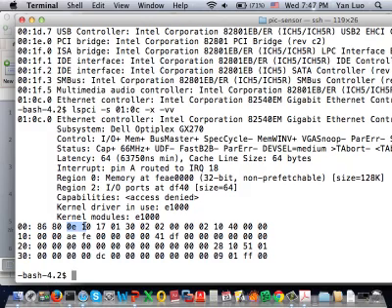And the following 2 bytes, 100E, is the device ID of a device produced by Intel. Intel has the authority to assign these codes to their devices. And by checking their database, the operating system finds out that this is a gigabit Ethernet controller, this particular model. If you look further, 0200, these 2 bytes represent the class. This is an Ethernet controller. All the Ethernet controllers will have 0200 as their class ID.